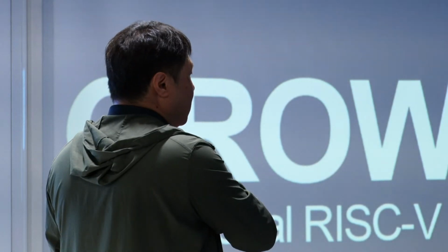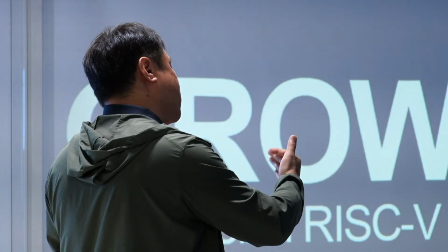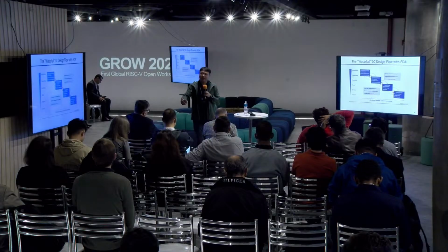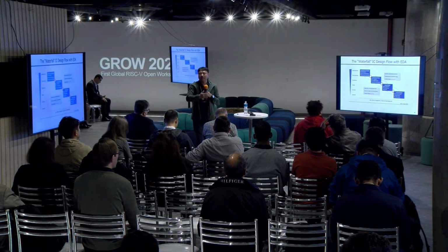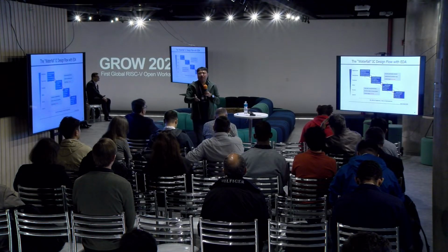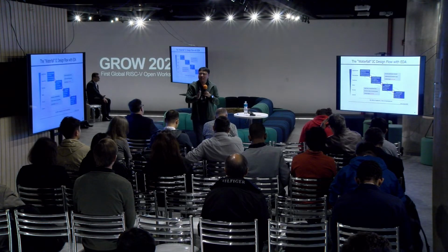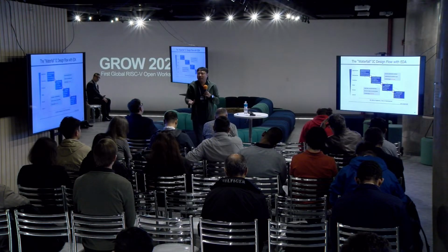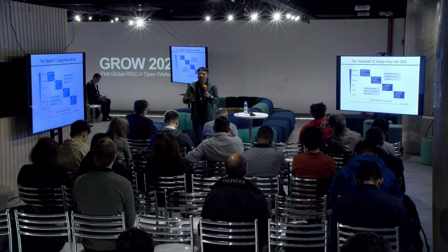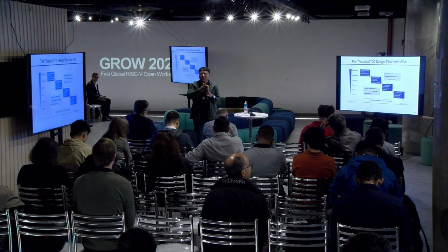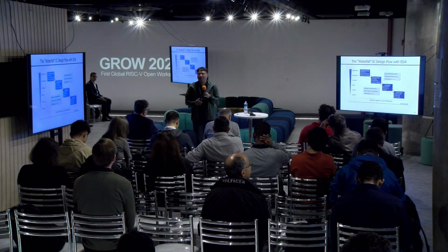So LLM is not good enough. You still need a model to learn your circuit and then generate stimuli that give you better coverage, right? And formal verification is a different story. SAT solving is a core engine of formal verification, right? So similarly, you can probably use LLMs to improve the heuristics you use in formal, but eventually AI is not guaranteed, right? And in formal, you want a 100% correctness guarantee, right? So you cannot use LLMs end-to-end, at least. So I think for both simulation-based verification and formal verification, there are lots of problems to be solved using AI.